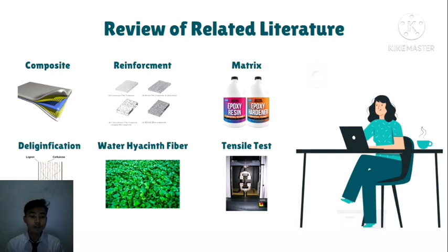And tensile test. Tensile test is a method used on material to determine the ductility and toughness of a material by applying a force load or tensile stress to the material. Standard tensile testing refers to ASTM D638-14.